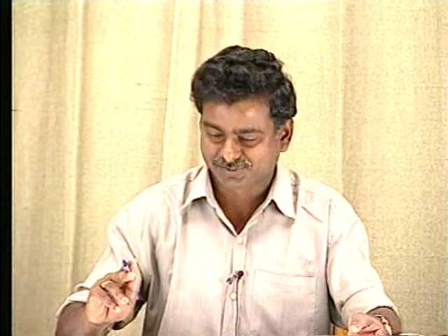Today I shall discuss the biasing of JFETs. The biasing is for the same purpose as I explained for the transistors. It is meant for operating the junction FET in the active region such that it works as an amplifier. When you apply an input signal, it amplifies the input signal and gives you a strong output signal. So for this purpose, biasing of the JFET is required. This is similar to the case of a transistor.